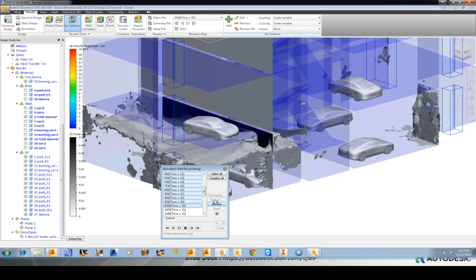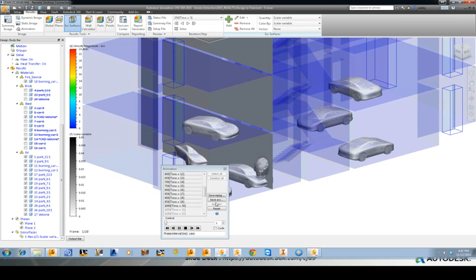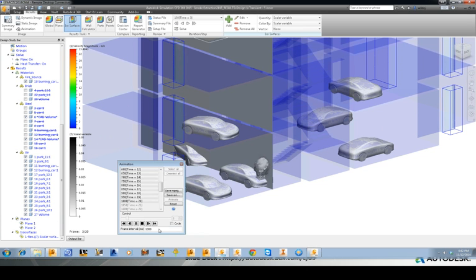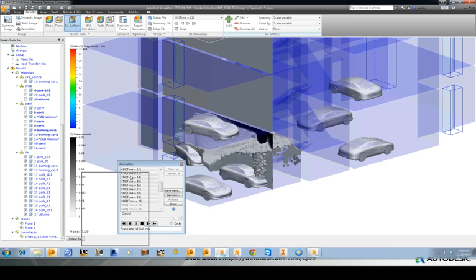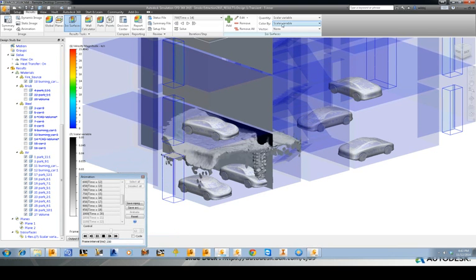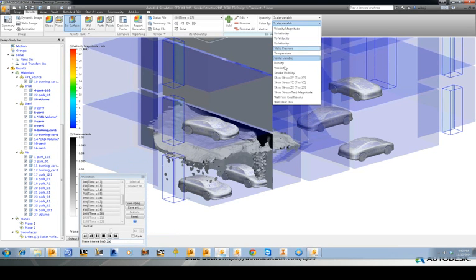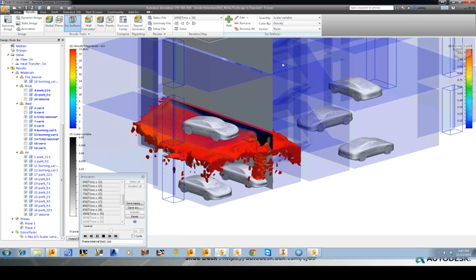And now we wait. What this is going to do is move with the view that we have, so that's showing quite a low scalar value, progressing from time 0 to 20 seconds. We can change the frame interval, so generally CFD takes quite a long time to get from one interval to the next. If we lower that a little bit, we'll see that spread out much quicker. We could also change the colour so we can see it a bit clearer. You can do all this on the fly and it will keep animating as you go.